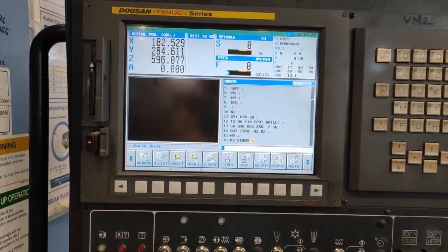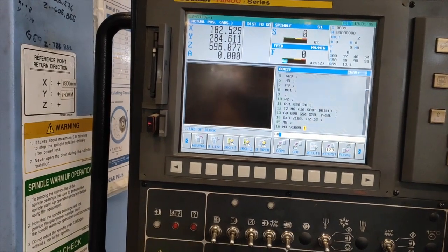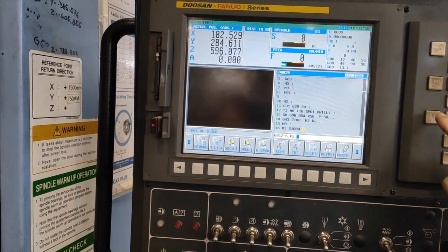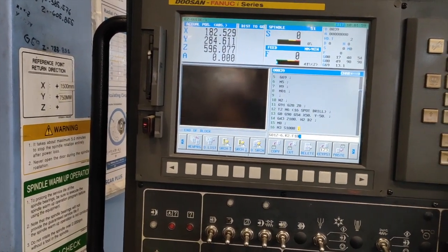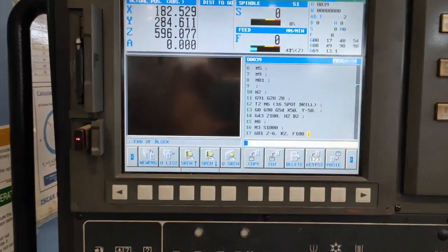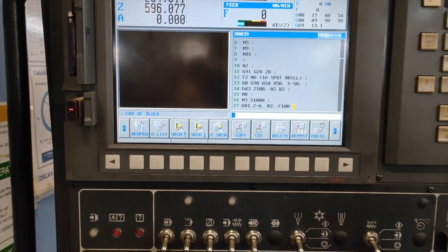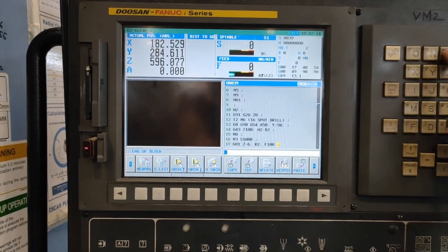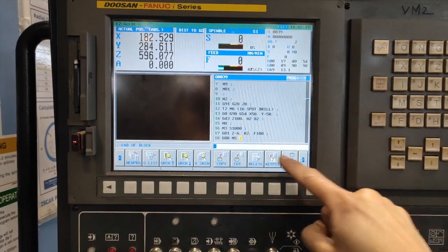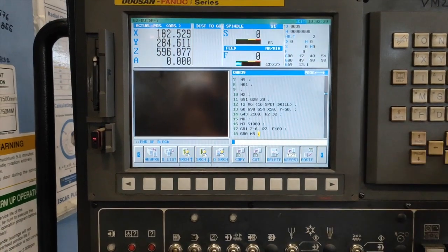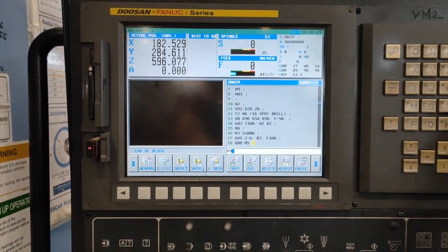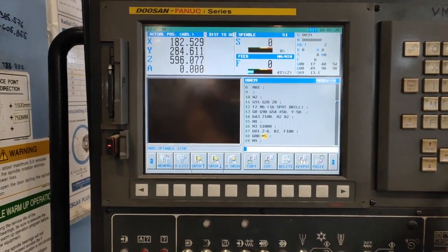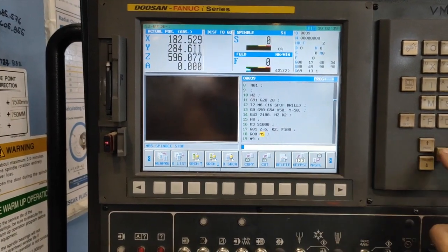and then your spindle is now rotating, G81, Z minus 6, R, then F, let's say 100. Now guys, I have the drilling for spotting, and I'm going to cancel the drilling cycle, G80 M5. So I'm going to put it in the same block. Then M9. So G80, guys, is cancel of the drilling cycle, and spindle up, coolant up.